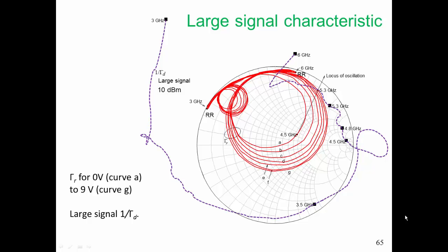So we're driving this circuit with a single sine wave. When our oscillator is oscillating, there will be some harmonic content there as well, and we clearly can't drive this circuit with harmonic content. So we're not creating a large signal situation that corresponds precisely to the large signal oscillation configuration, but we are seeing what we expect.